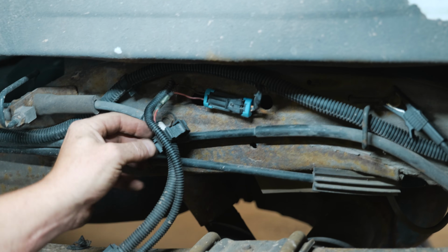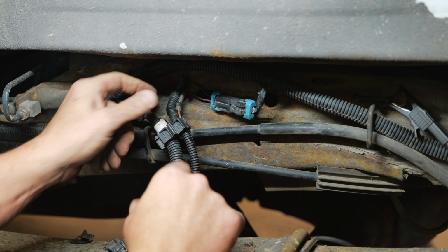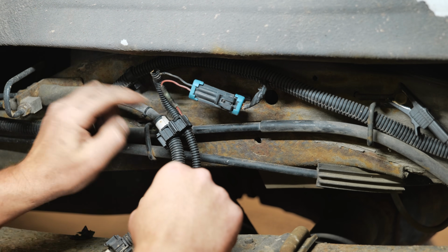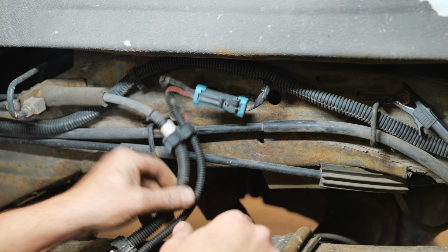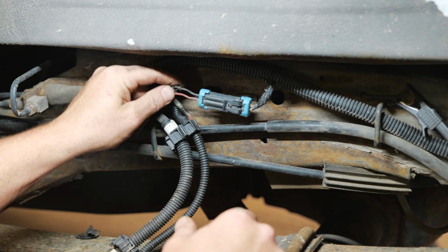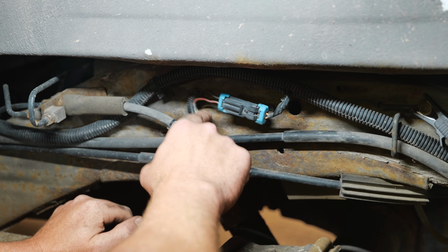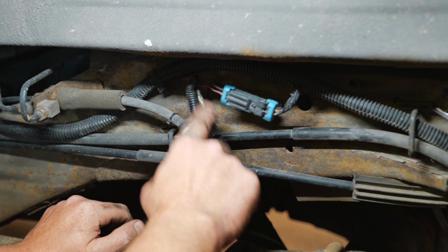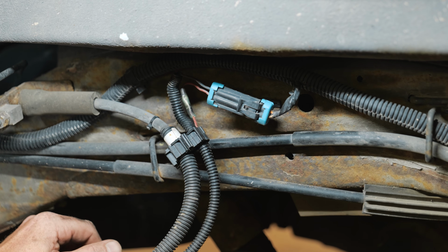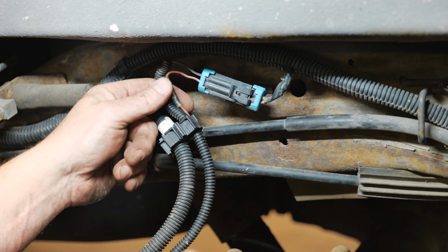That is not a good fix. If Pete can't get this sub harness, I'm gonna have him use some of that Tessa tape and tape this up, because that's gonna end up doing the same thing over time. This is what caused it, right? I think maybe I might have been laying over here, but just up and down vibrations. If you can't get this sub harness, Pete, I want you to tape this up better right here. Okay? All right, cool.